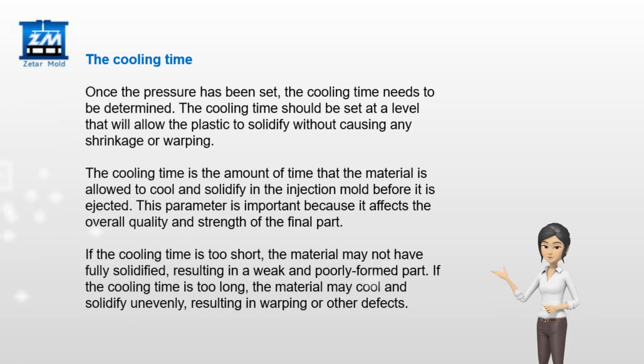This parameter is important because it affects the overall quality and strength of the final part. If the cooling time is too short, the material may not have fully solidified, resulting in a weak and poorly formed part. If the cooling time is too long, the material may cool and solidify unevenly, resulting in warping or other defects.